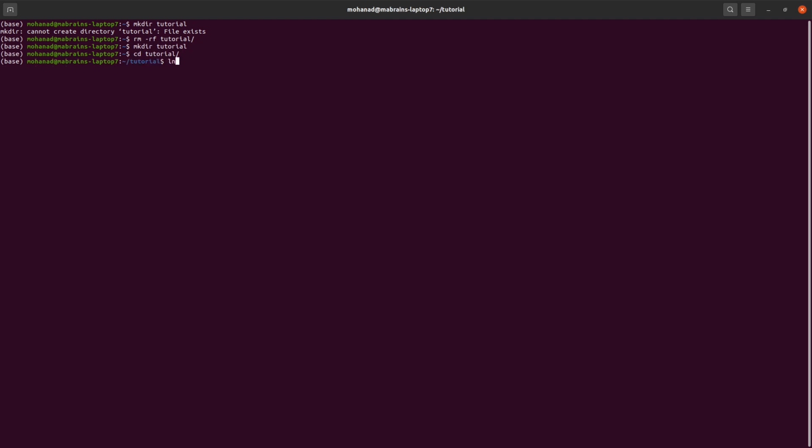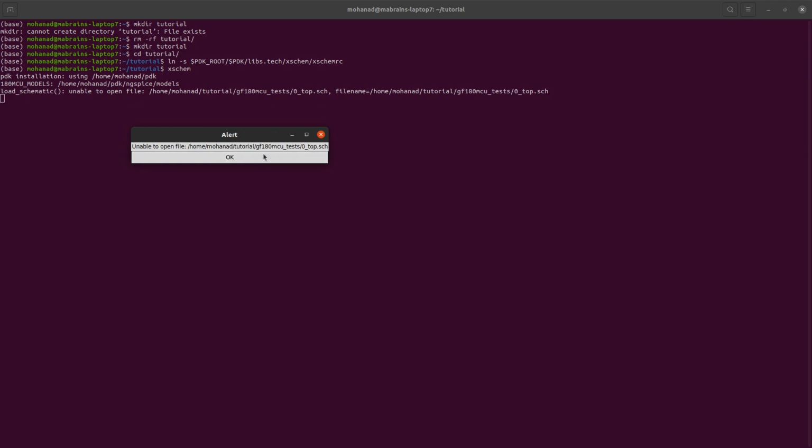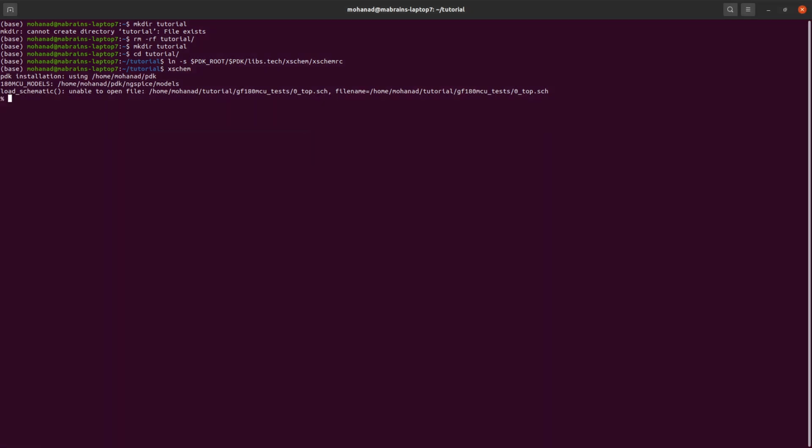Now, I will link the file that we talked about, which is located in PDK_ROOT, the PDK, libs.tech, xschem, xschemrc. Now we can run the tool. As you see, I got some errors. These errors we need to solve. So simply, we will be editing the xschemrc file.